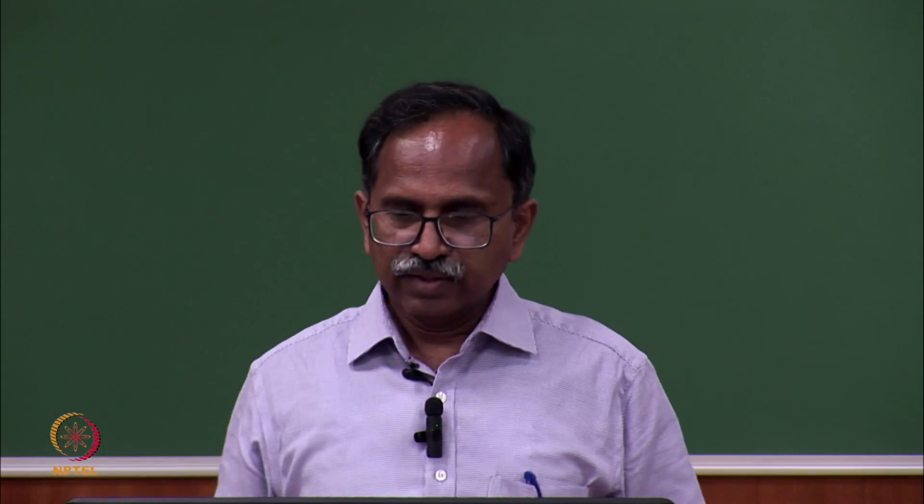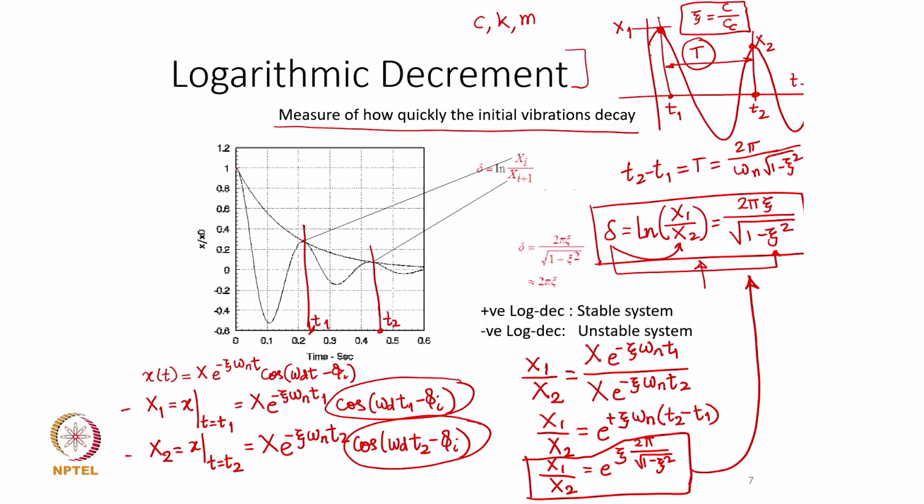So, if I can capture this vibratory response, measure it, the sensor will give me a measured vibration response like this, and then from this measured data I can find what this x1 is, I can find what this x2 is. So, from the measured values I can get to know the damping and the level of damping in the system without worrying about how much mass the system has, how much stiffness the system has. Okay. So, knowledge of the system parameter values is not essential here.